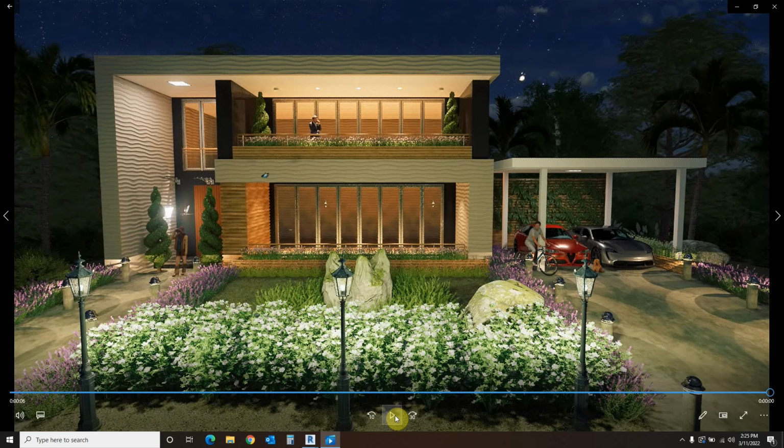And with that, we have seen how to create our model in Revit, which was not really part of this, but we start with that. Then we went ahead and made some adjustments to our materials using some Enscape materials. Then we imported some Enscape geometry, and we saw some of the things we have to pay attention to, such as making sure they're in the proper plane so they don't look like they're sunken or swallowed by the earth.